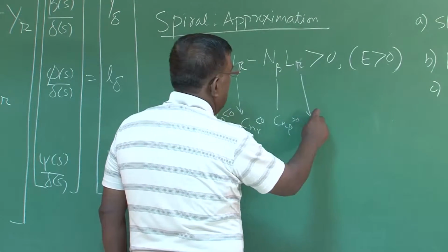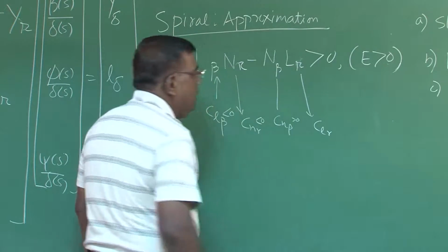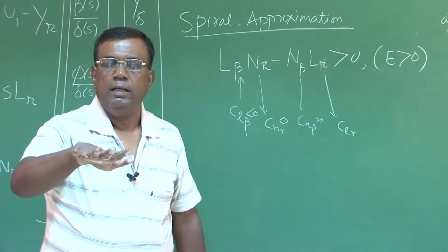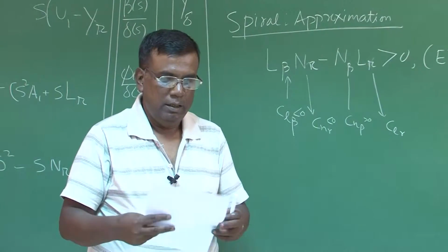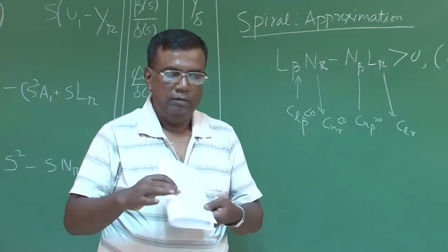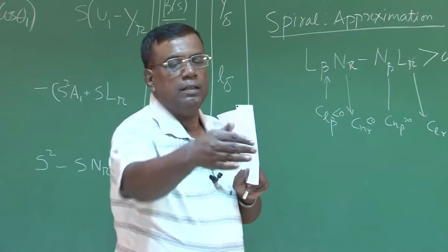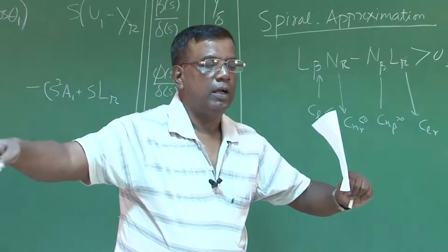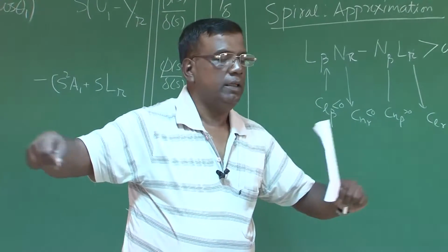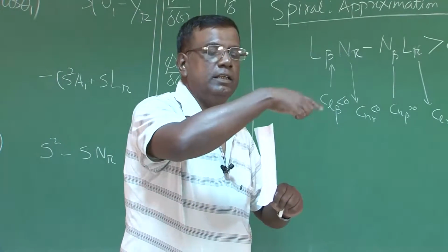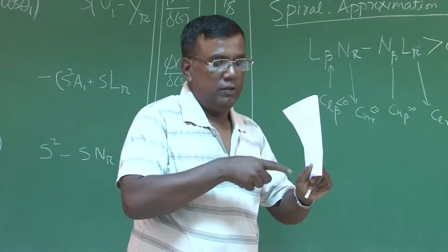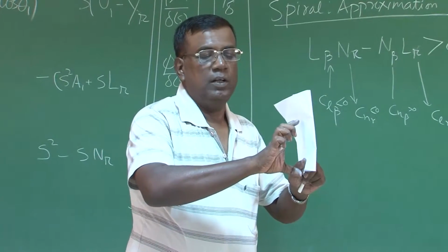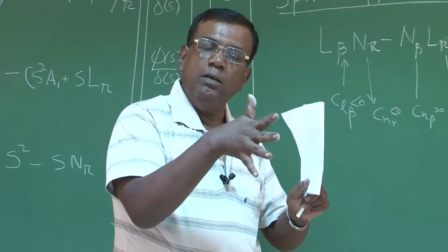And this is CLR. And CLR, you understand, if the airplane is having a positive yaw rate like this, let's say, and this is the vertical tail, as it goes positive it is pushing the air in this direction. It will experience the force in this direction, and this force into the distance from the fuselage center line will give me a rolling moment.